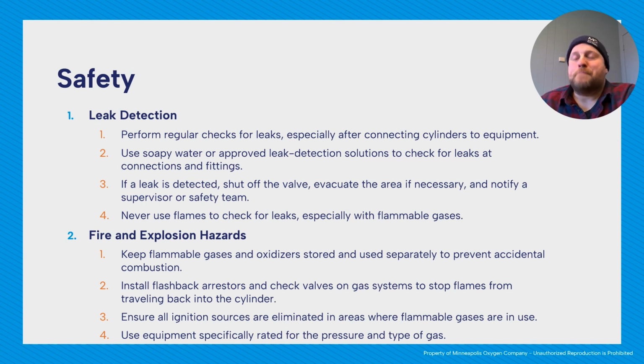At best, you could prevent either poor weld quality from atmosphere getting into the lines, or if it's a fuel gas, you're preventing an explosion or something very serious happening. So I definitely suggest doing a quick leak check every time you hook up a new cylinder.